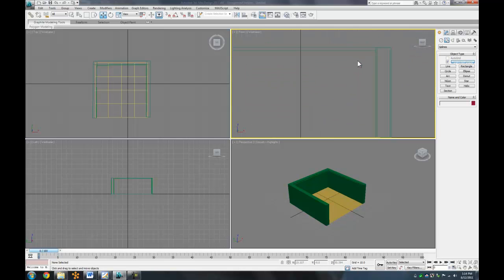We're going to take our front viewport and zoom into where that spline would be. Doesn't matter where it's at right now. We're going to grab a line. We're going to grab a smooth drag type and a smooth initial type. This is the first point we make. What we're going to do here is click and hold, and when I let go of this button, it's going to start to curve. So we've got a simple ellipse, looks like.